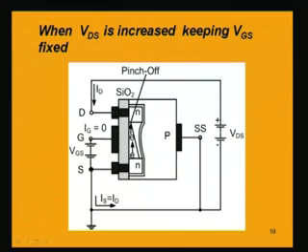But if we go up, the voltage between the gate and that point is not the same as the voltage here. So, if we go towards up and finally reach the drain, then the voltage between the gate and that point on the drain will be equal to VGS minus VDS.